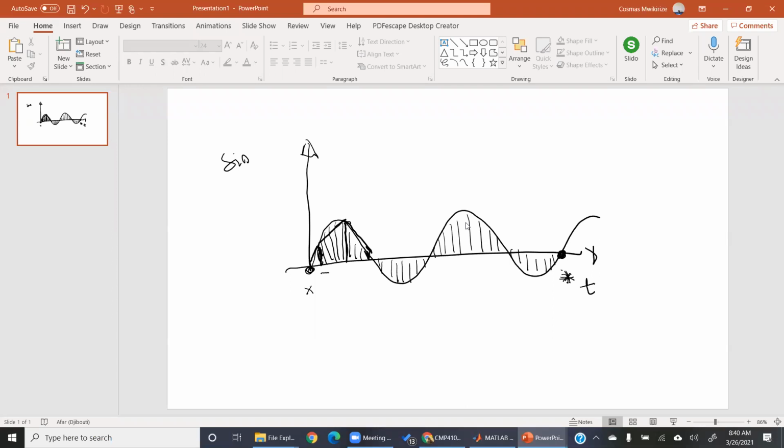So when your sampling frequency is low, meaning that your sampling period is high, because that's the time between the samples that you're acquiring, then your signal reconstruction is going to be a bit haphazard. So you want a high sampling frequency.